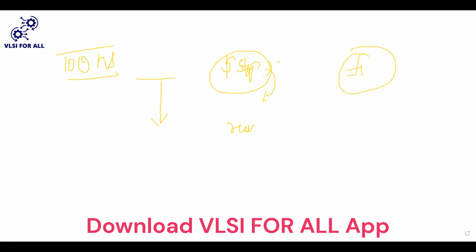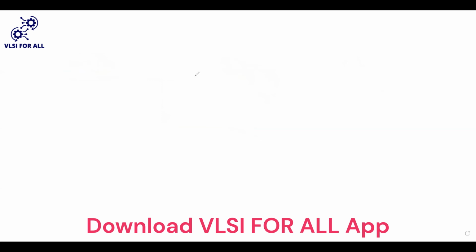And finally, generating a random number in Verilog. How do we generate a random number in Verilog? The basic idea is that we need to use $random. Basically, $random may produce erroneous results. Based upon whatever value we have taken, either an integer or anything, it can produce any values, and they can be either signed or unsigned. If I want those values within a particular range, this $random will generate random values.